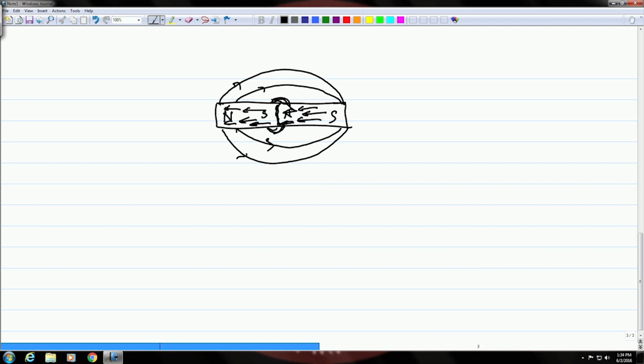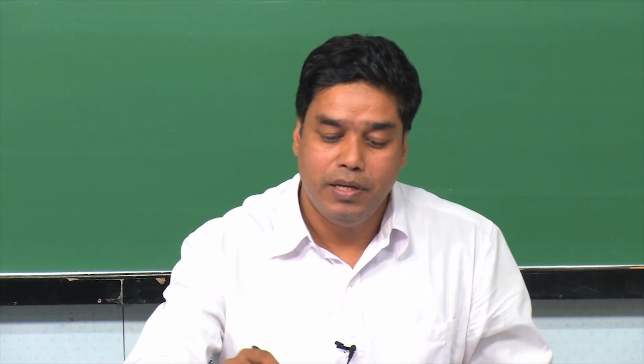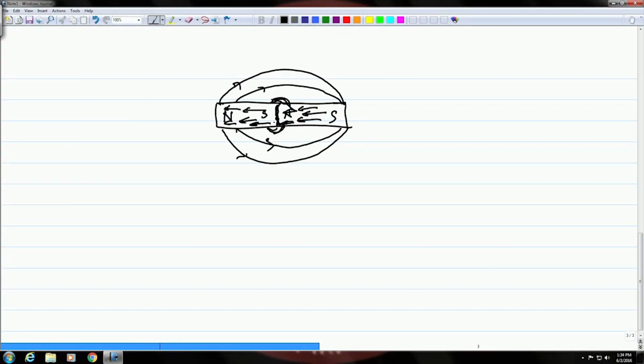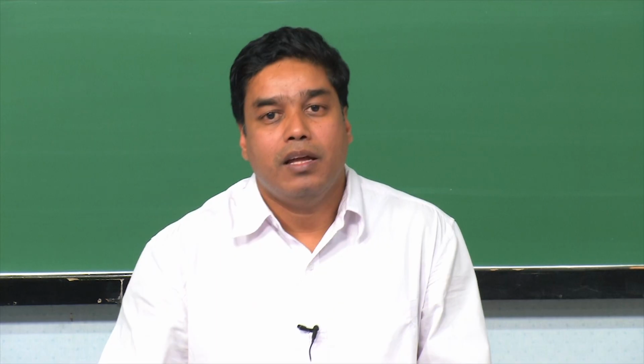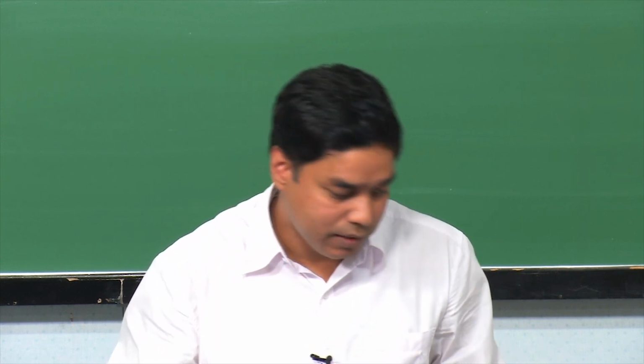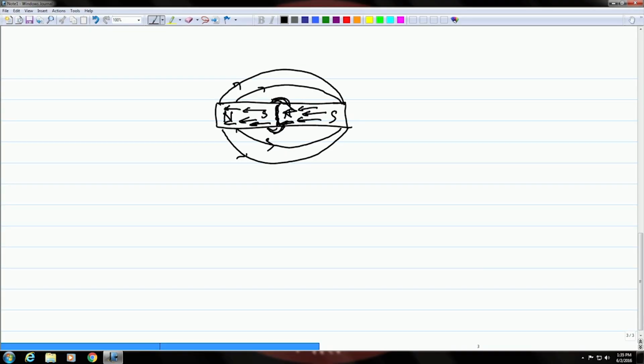So, now if you apply some magnetic particles like iron, they will be attracted to this discontinuity, because now it is magnetized, and that is how they will accumulate along this crack and make visible indications. So, this is as simple as that. Due to the flux leakage at the defect, a small tiny magnet is created, which will attract the magnetic particles and make visible indications.